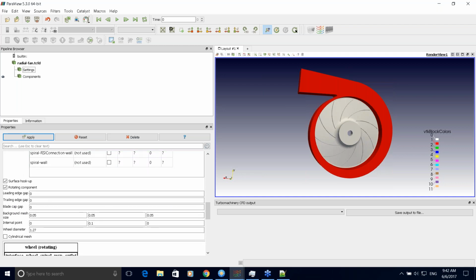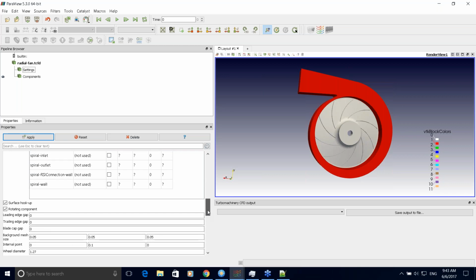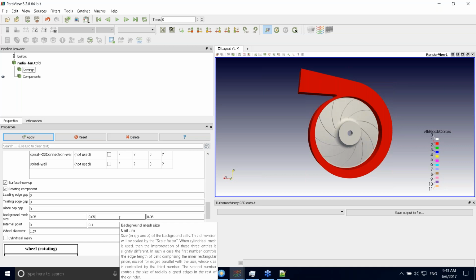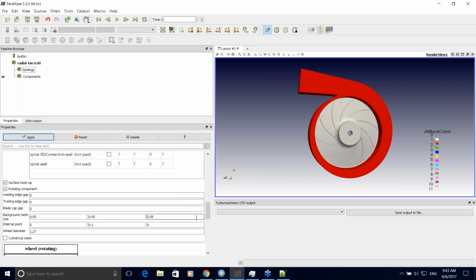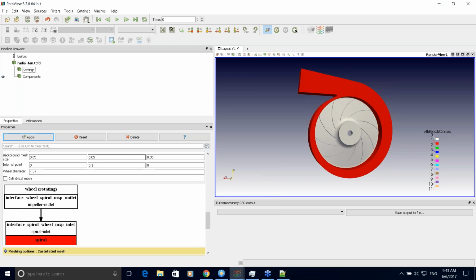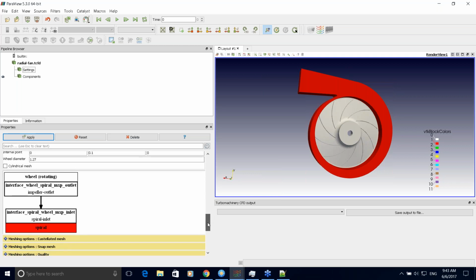Okay, and here are other parameters to set. If you define the geometry from STL, so you should define the finest of the mesh. Again, it is set in default, but you can modify it. For example, an important parameter is the background mesh size, which is the largest cell in the computational mesh, and more parameters to be set.